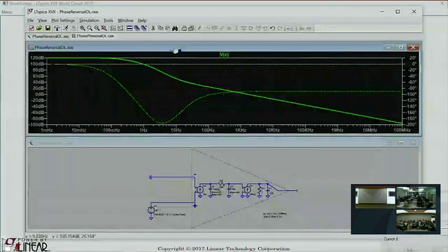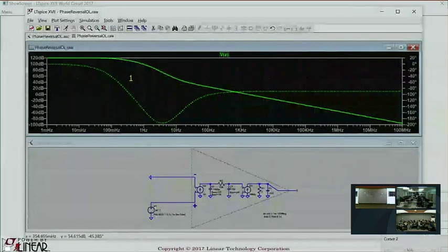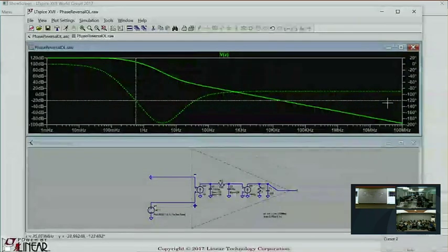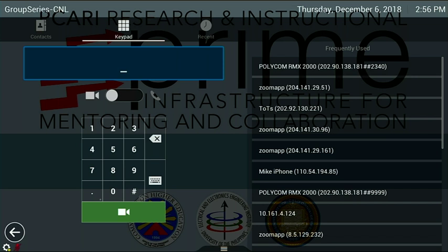So let's increase frequency and see how the shift goes. Higher frequency, higher frequency. There's 120 degrees phase shift, so if it went through crossover at that point, the phase margin would be 60 degrees, which many people feel is a happy number, but oh no, I've got lots of gain at that frequency. Let's continue. Here's 160 degrees phase shift.